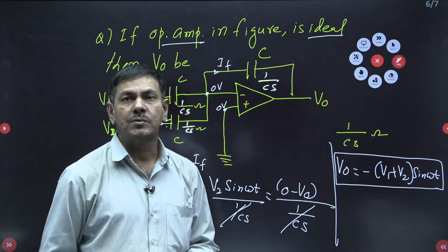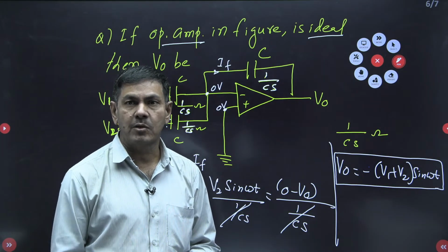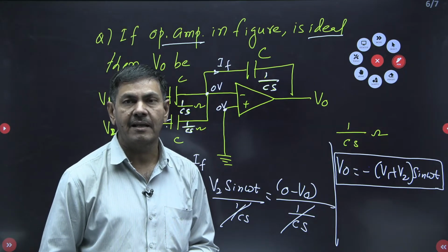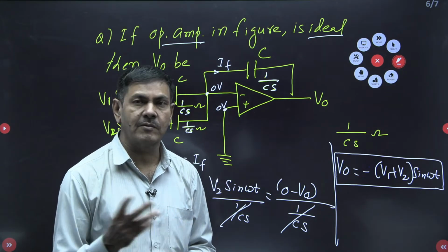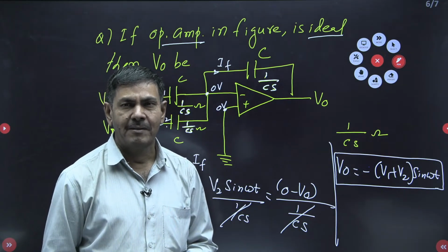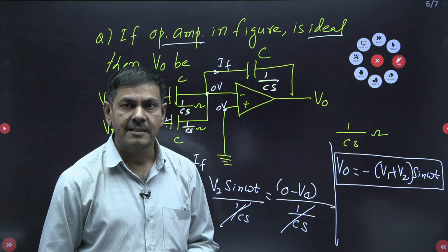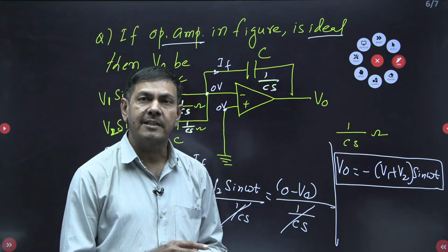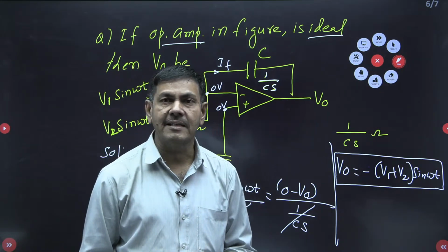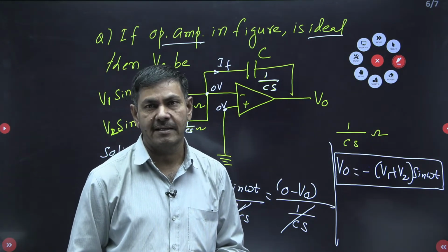When you want to generate frequency in kilohertz, you use the Wien's bridge oscillator or the RC phase shift oscillator. Any one of them can give frequency in kilohertz, but the frequency range of the RC phase shift is more than the Wien's bridge. The next ones are the Hartley oscillator and the Colpitts oscillator.